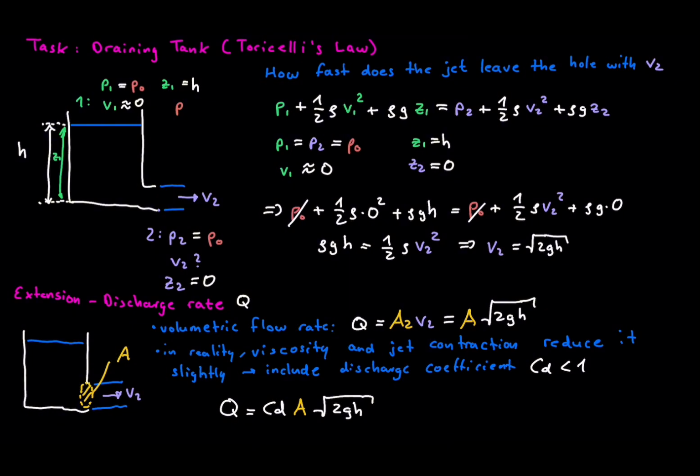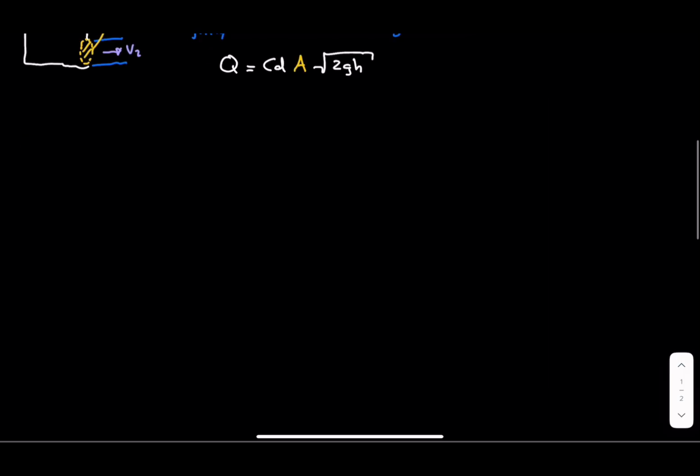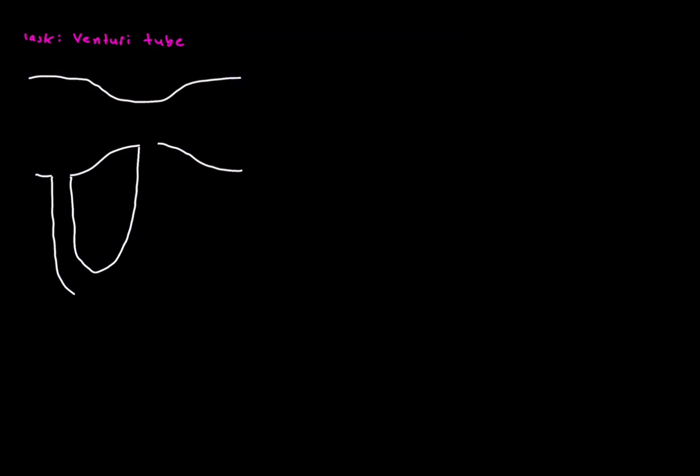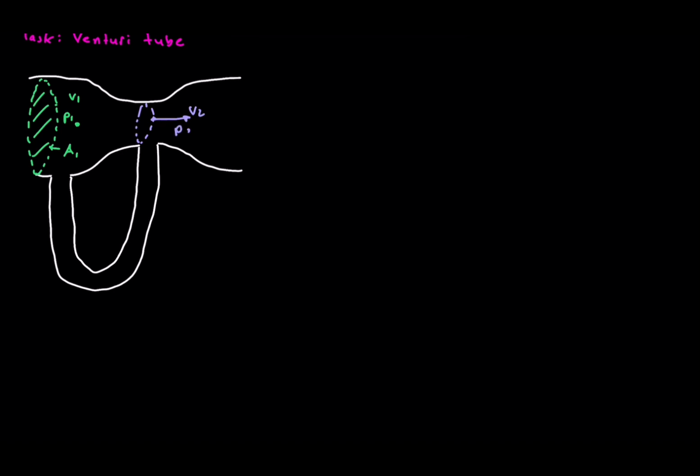Now let's measure flow. The Venturi meter. Imagine a smooth pipe that narrows in the middle and then widens again. The wide section has area A1 and the throat has area A2. We measure the pressure at both sections with 2 small taps connected to a U-tube manometer. The height difference of the liquid column tells us the pressure drop between the 2 points.